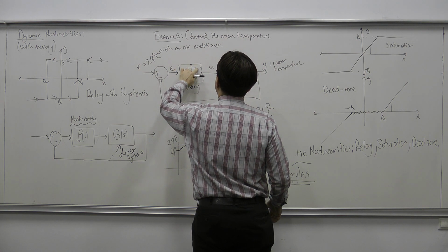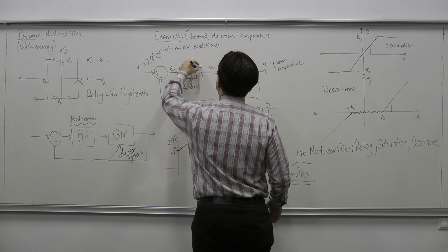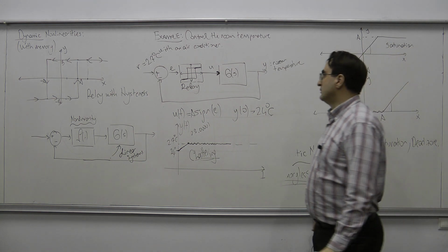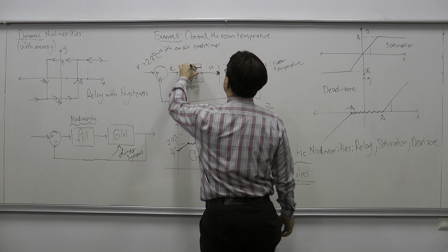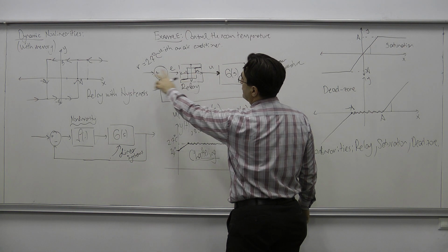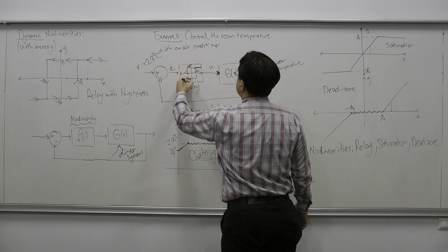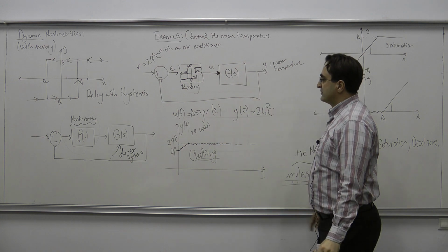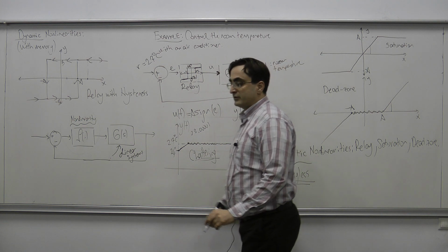In that case, it will be just like this. So it's going to be similar to a relay, but it's going to have a hysteresis in the middle. Okay? Let us say that this point is -2 and this point is +2. So these are the limits of the hysteresis behavior. So A is just 2 here, all right? So here I have +A intensity and -A intensities here. So the same intensities, but I would have -2 +2 limits hysteresis, okay?